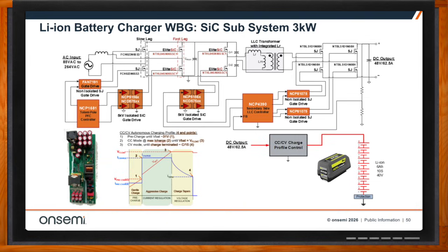And by doing that through an isolated gate driver, the 1681 totem pole PFC, using that, you can jettison the full wave rectifier you typically have for a power supply. That saves on the form factor. It allows you to reduce the form factor, and it increases the efficiency because using the full wave rectifier diodes are a lot less efficient.